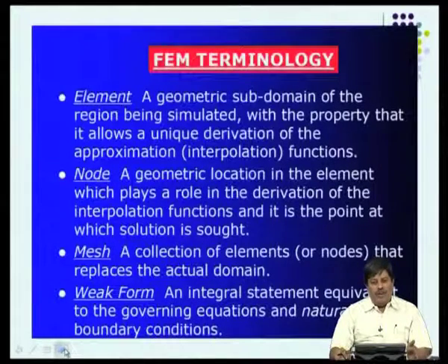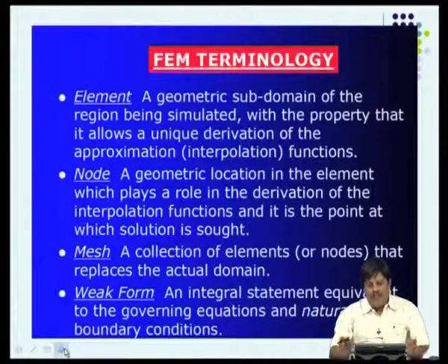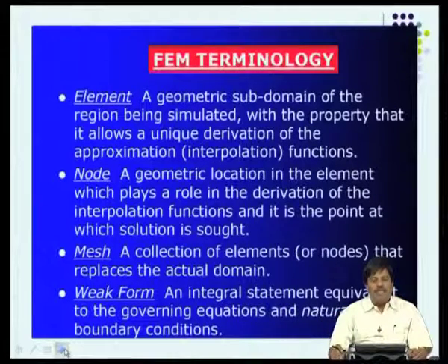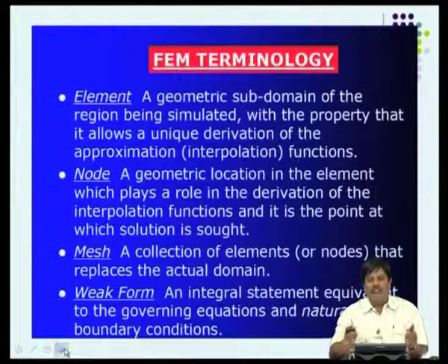A node is a geometric location of the element which plays a role in the derivation of the interpolation function, and it is the point at which the solution is sought. Even though we are talking about a continuum, we seek the solution only at nodes. Mesh is a collection of elements or nodes that replaces the actual domain.